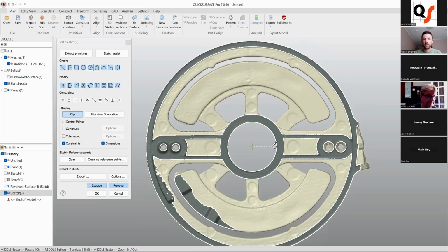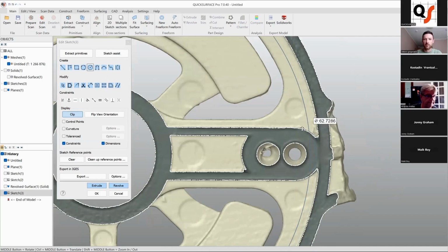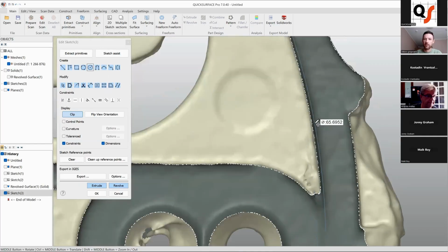So I'm going to use the center point of the part initially and just drag it up to mesh points from the part, which we assume as non-defective. Here, if you press Control, it automatically snaps to the same mesh points.